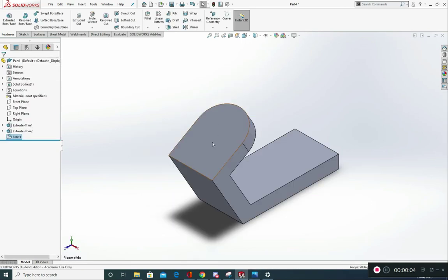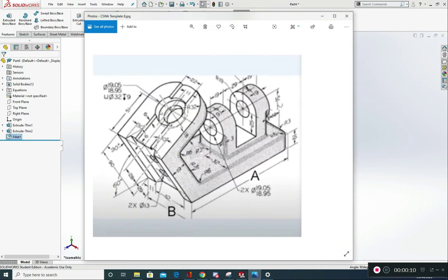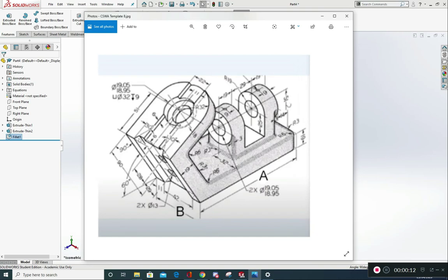Okay, so the next bit I'm going to focus on is this bit here, and a little slot that goes down here as well. I'll just show you on here. So what we've got is this kind of cutout section here that I've got some dimensions for. So this 11, this 42, I've got a 60 degree angle in here, and 60 plus the 30 would give me a 90 degrees.